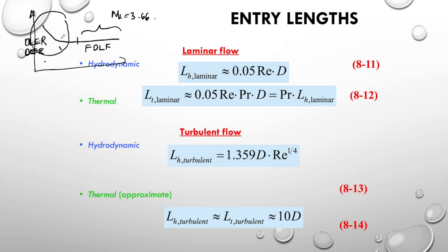As the x increases, the Nusselt number decreases. Let's say you have your Nusselt number at 37.6, and it will reduce up to 3.66. And after it is fully developed, it will be constant. The Nusselt number would be constant at 3.66. This is fully developed laminar flow.